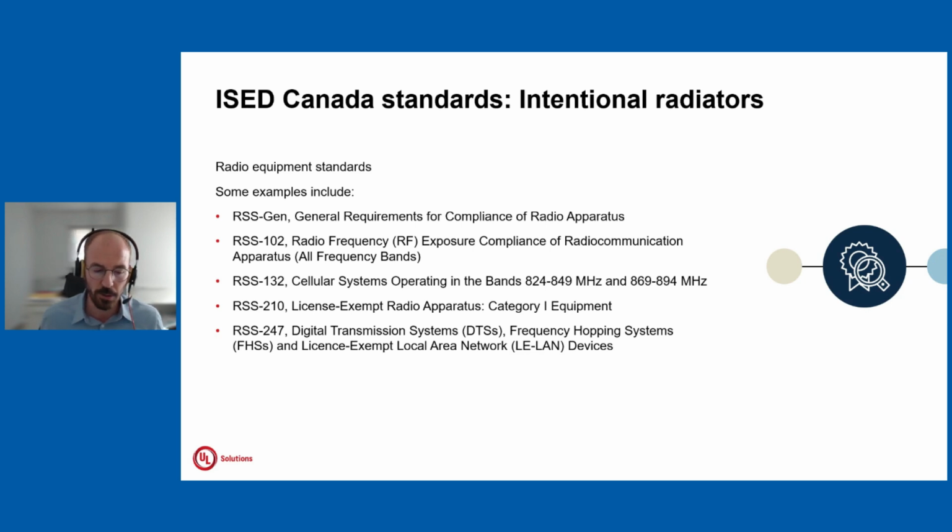You also have a look into this RSS-102. What you also need to be aware of is when we are talking about radio testing. If you are familiar with the Radio Equipment Directive, you know that the Radio Equipment Directive has multiple requirements: it has the EMC requirement, and the radio spectrum requirement, Article 3.2. But there's also Article 3.1a, which is human exposure to electromagnetic fields. You need to remember the fact that a radio transmitter generates electromagnetic fields to operate. And these electromagnetic fields are somehow absorbed by human skin. And obviously, this can create health issues.